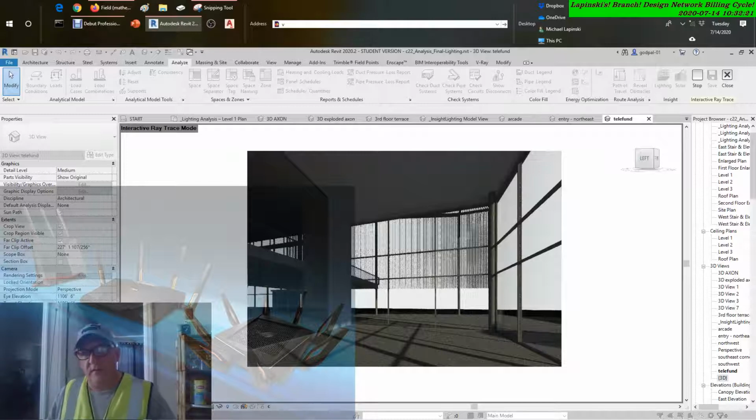Target percentage glazing. This value sets the assumed amount of glazing as a percentage of the overall wall area. Target sill height. This is the height of the sill for glazing to begin on each floor. Glazing is shaded. Select this box if you intend to design sun shading for the glazing. This does not differentiate by building orientation, so if you check the box, conceptual shading elements will be added to the glazing assumptions on all sides.